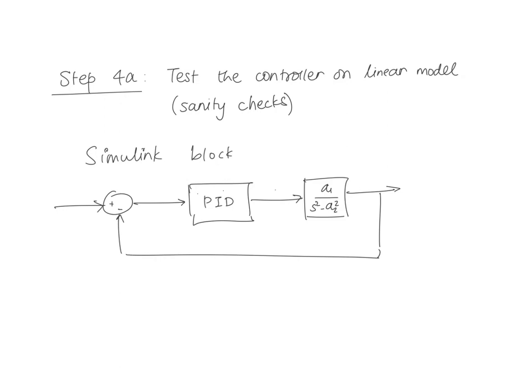Okay, and here put an impulse. You'd like to find out what happens to the system if it's hit by a disturbance or if it starts from a non-zero initial condition. So it starts slightly off from the vertical, for example. To test it, just put an impulse input, and you can construct an impulse input in Simulink as a step input followed by a derivative. There will be a delta U over delta T block in Simulink.